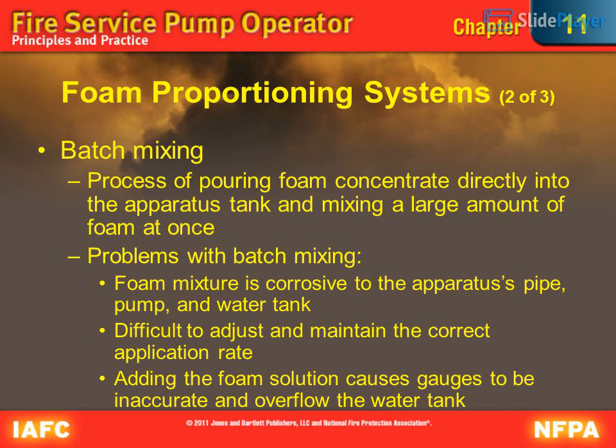Batch mixing. Process of pouring foam concentrate directly into the apparatus tank and mixing a large amount of foam at once. Problems with batch mixing. Foamed mixture is corrosive to the apparatus's pipe, pump, and water tank. Difficult to adjust and maintain the correct application rate. Adding the foam solution causes gauges to be inaccurate and overflow the water tank.